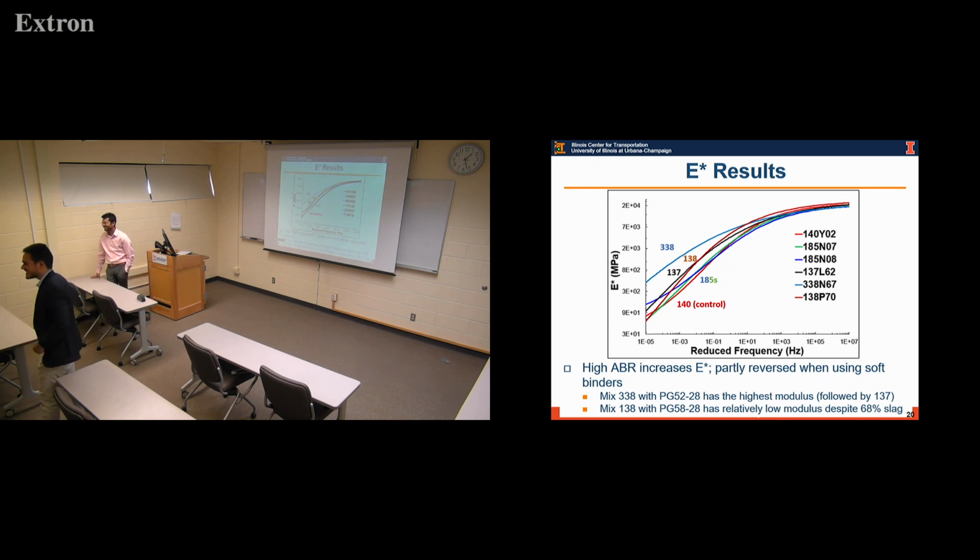I have a quick question regarding the DIC technique. I saw the pictures where you highlighted these fracture or cracking areas. How do you find these areas? Do you do that manually or automatically? With MATLAB. From the DIC, what you get is the whole matrix of the picture: each point of the image and the strain that you are measuring at each point, which we call a subset.